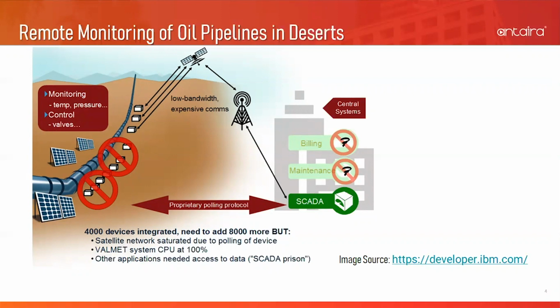Firstly, there was a natural delay between the time of requesting and receiving the data due to the satellite's position changes, which resulted in timing gaps. The SCADA saw these timing gaps as error conditions because all these polling and responses didn't happen in a preset time interval. Secondly, it wasn't feasible to expand capacity by adding more devices.